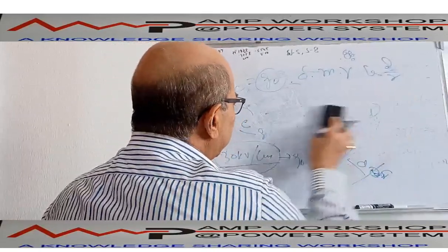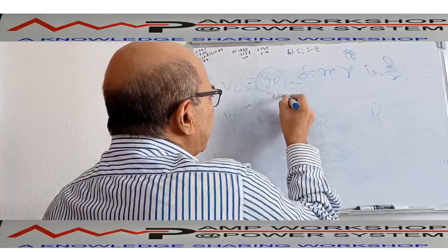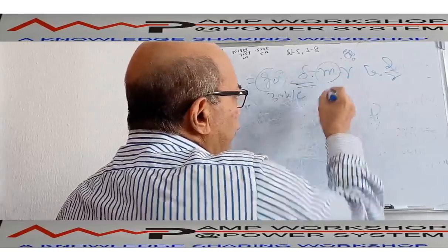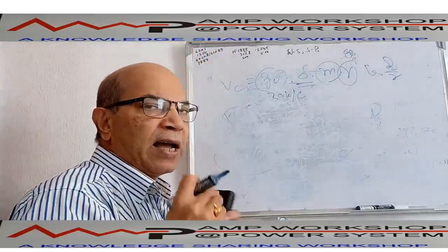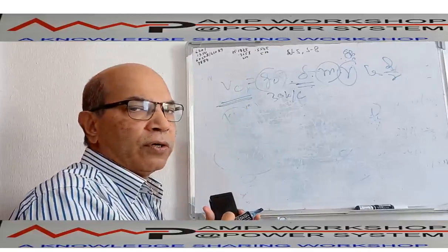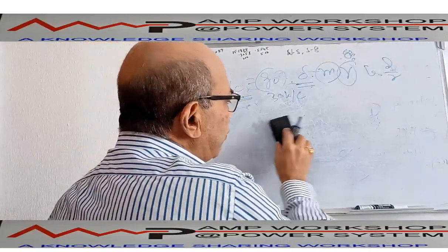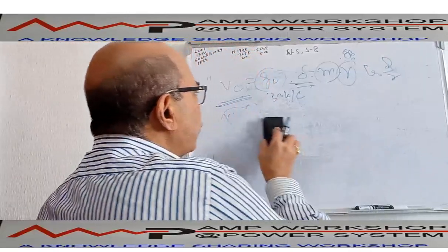That means this critical disruptive voltage, with 30 kV per centimeter, depends on the air density, smoothness of the conductor and the conductor radius. So if you make a conductor of bigger diameter, then the critical voltage will be more and more. Disruptive voltage will be more, so immediately it will break down, and the corona discharge will be more.